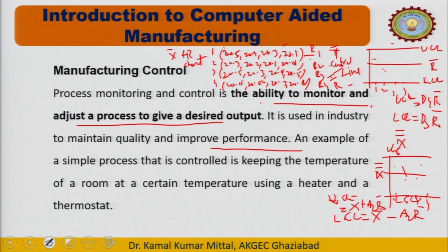We are using a feedback sensor which will give feedback to the controller. The controller will control and give a signal to the actuator. It means if our temperature is 30, it will increase, become 32, 35, and when it becomes 40, equal to the initial parameter. Ideally it is not possible, but close to zero, the difference between the input parameter and output variable is close to 0, then the feedback sensor sends a signal to the controller, and the controller sends the signal to the motor or compressor which we are using, that acts as an actuator, and that actuator or compressor will stop its work. So in this way our temperature will be maintained.